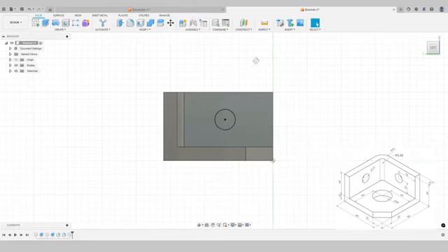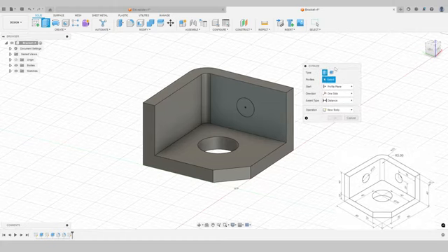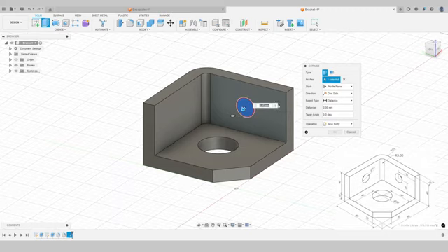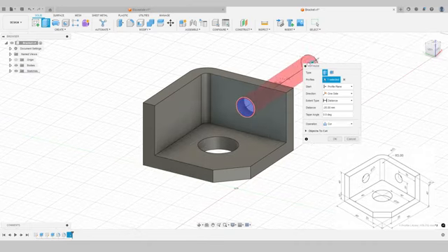Let's go ahead and finish that sketch. Now we need to extrude cut. So we need to remove the material. So again, we'll select the extrude tool. Under here, we'll select our profile, which in this case is this profile here. Then under distance, we see the arrow here. So we can hold down the left mouse button and pull that out to extrude and add material, or in the other direction, we can remove material. So I'm going to put in a distance there. Going to be accurate. Put in a distance of minus 10 millimeters.